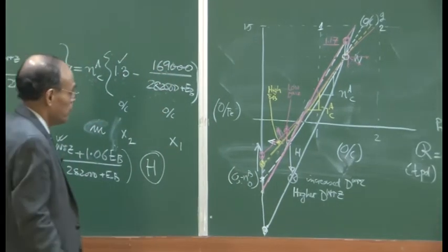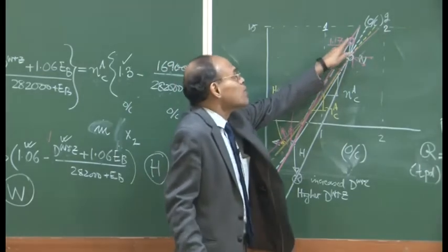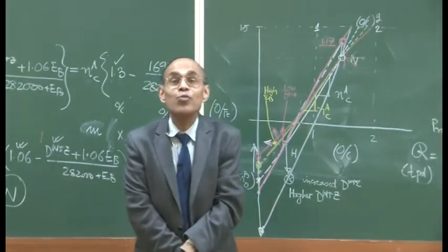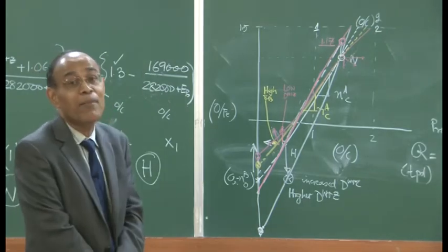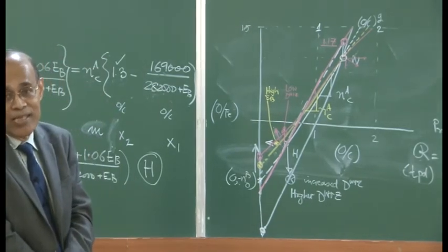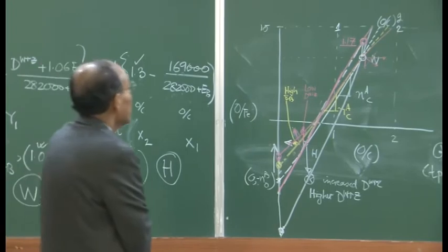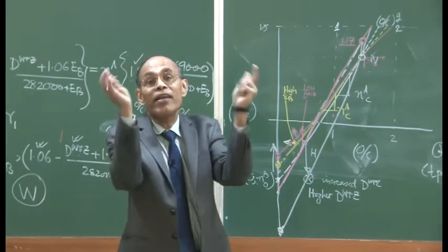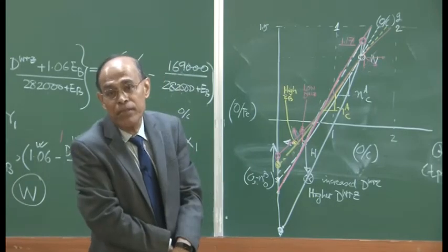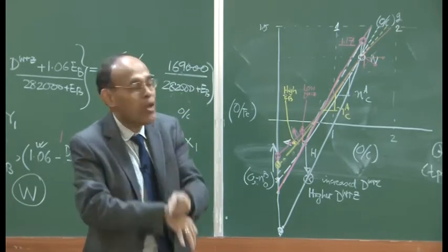And how could this point 1.06 be smaller? It could be smaller if you incorporate metallic charges into the blast furnace itself. For example, relative to oxygen, if you have more metal charge, such as if I charge scrap steel into the blast furnace.